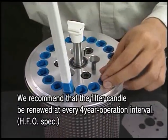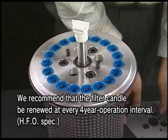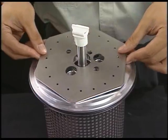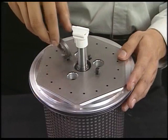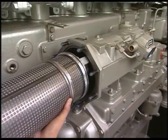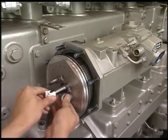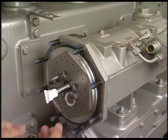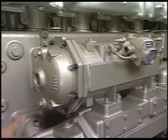Put the filter element in the main body, return the upper plate, and then insert it into the main body. Change all the O-rings when fixing. Rotate the flushing shaft slightly and engage the gear with the driving pinion of the reduction gear. Finally, fix the cover and the work will be completed.